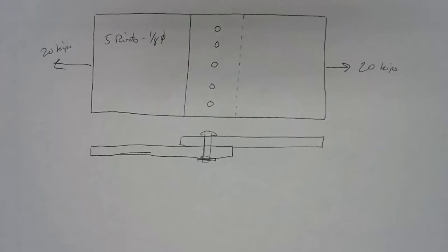But it's better if we spread that load out. So what we really do when we're going into those W tables and such, what we're really doing is we're finding the area of the pin we need to handle that force. And then we just split it up into a certain number of rivets. So when it says use 12 rivets for this lap joint, well, then that means that 12 rivets is enough area to hold that joint together.